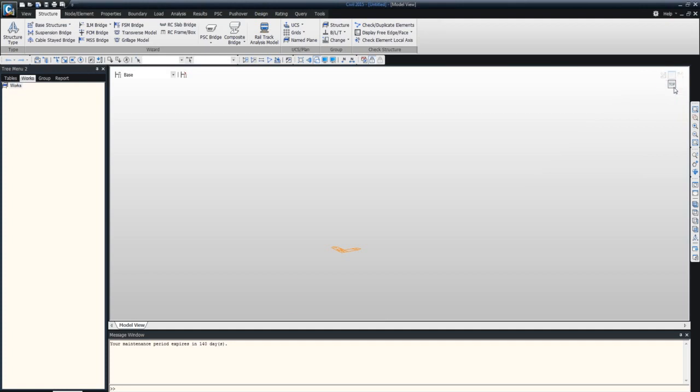And if you go to the top right here, as you can see, this is your coordinate system. You can click on these arrows and these tabs to change your view. And then these icons over here control your view settings. I'll go over these a little bit later. And then these options over here are your selection filters that allow you to select certain elements or to unselect things, etc. Okay, I understand it's a lot to take in right now, but as you see me create the model, you'll see that it's very easy. It's very intuitive as far as the way everything's set up.